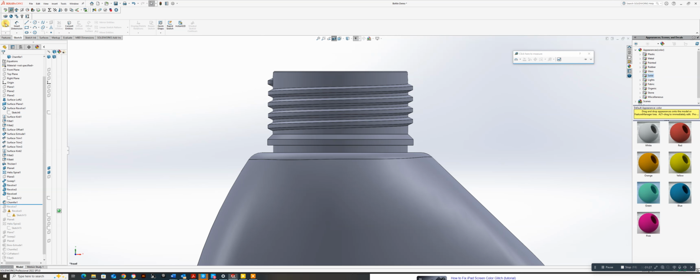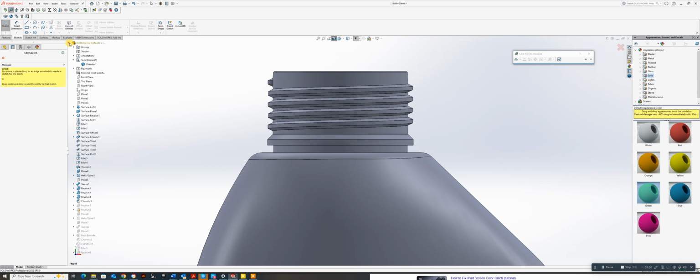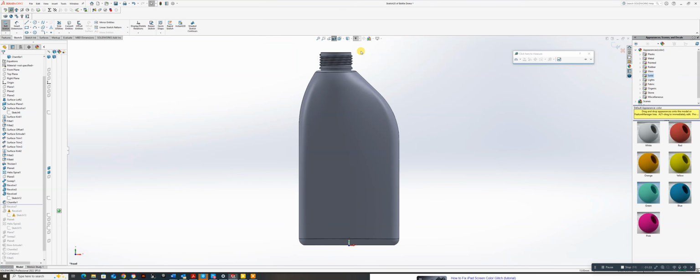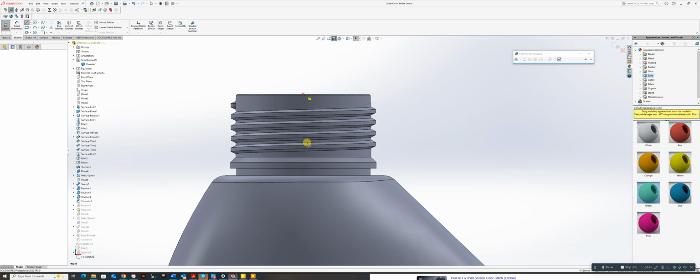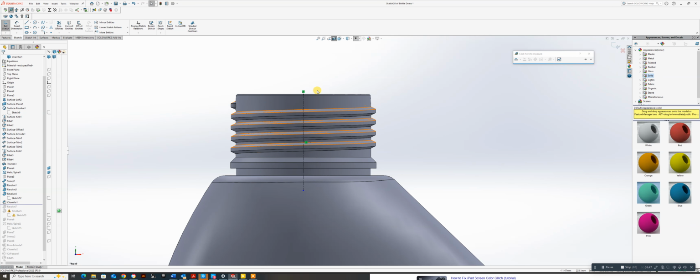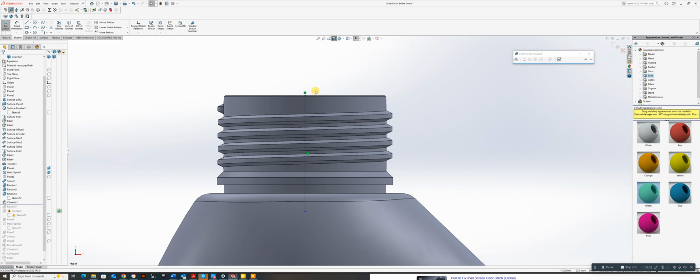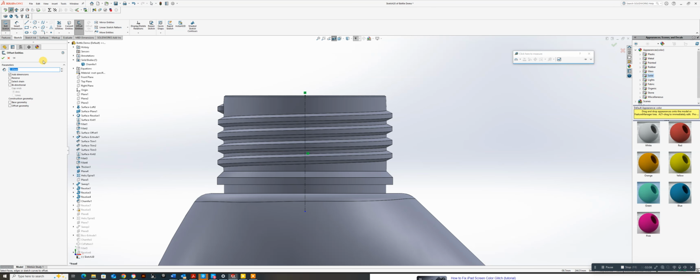To start with, I'm going to go to sketch, and I'm going to use front plane, which is up there, which is quite easy. First things first, I'm going to put myself a centre line in, from that point there to anywhere down there, it doesn't matter. I'm going to give it an indefinite end, but as long as I've got some sort of anchor and it is black. Now I could just draw this out, but I think we can use a combination of offset and normal drawing. So I'm just going to go to offset entities, and I want this at 0.1.